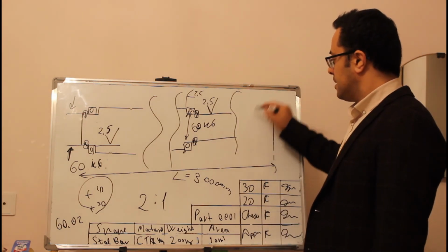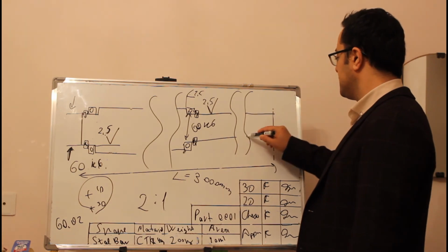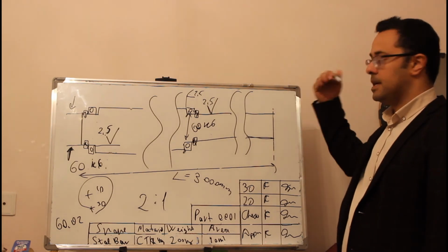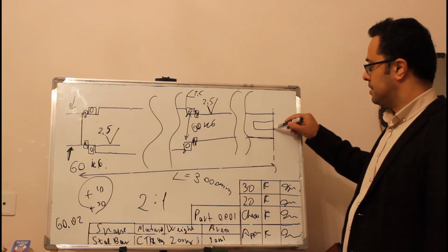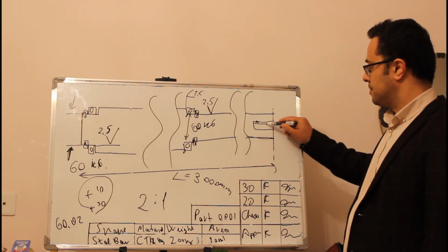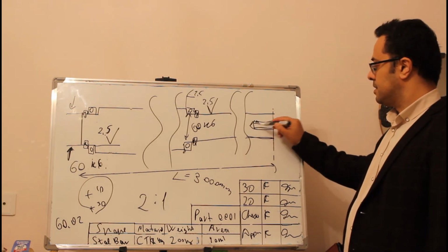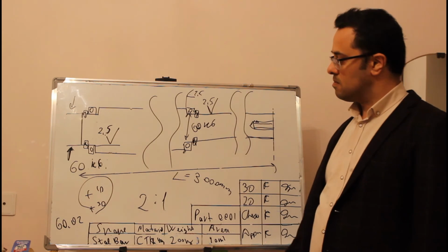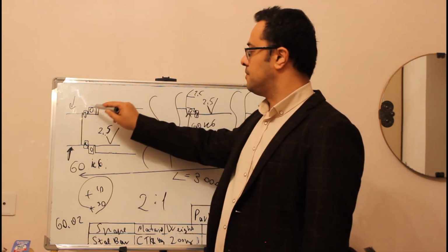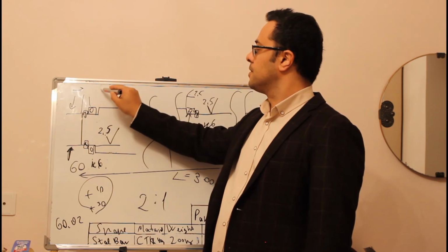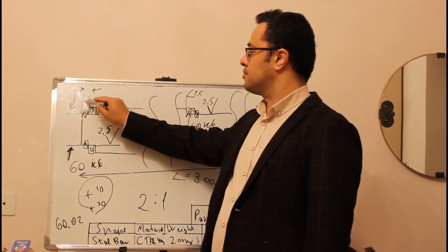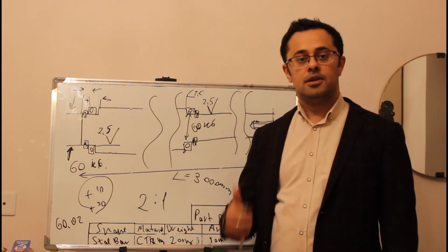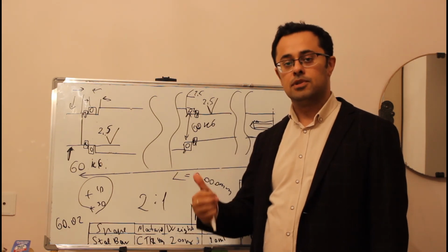Yeah, I put another line here and finish the shaft. At the end of shaft there will be another part. I'll put the threaded hole here. It's threaded so you can put your bolt there. So I'll show you dimensions like these dimensions. I have to show this dimension. You have to show all dimensions as if you are gonna machine it. That way you will understand what is missing and what is not.